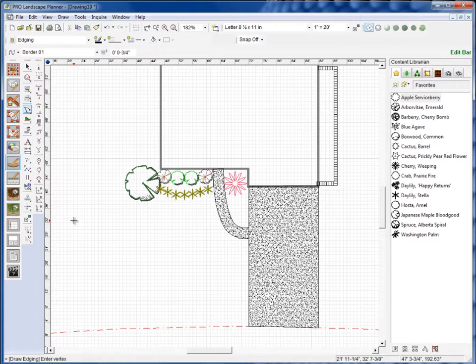Okay, let's first talk about the different line types that we can draw with. If we go up to our edit bar, you'll click on the first tool here, and this is going to be the different line types. We have a straight line, which is simply a line from point A to point B, or a polyline, which will go from point to point, and it'll have straight line segments in between the lines. We also can do a semicircle. We also can do a spline and a fitted curve. Let's go ahead and show you the differences between the polyline and then the different types of curves.